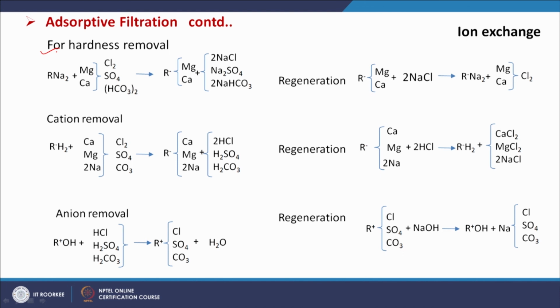Here the reagent used is in RNa2 form, and calcium, magnesium and other cations present in the solution are attached by the R part and Na is released, and Na salts of the anions are formed. When we go for regeneration, NaCl is added again because we have to make RNa2.